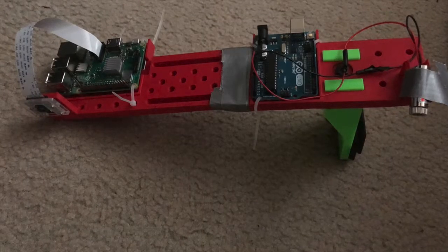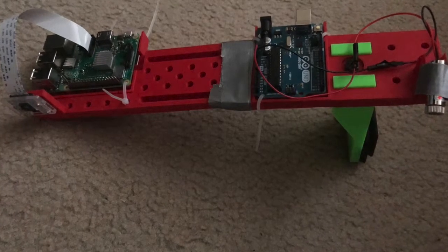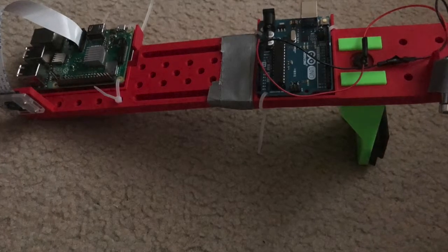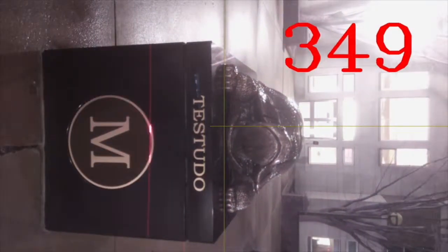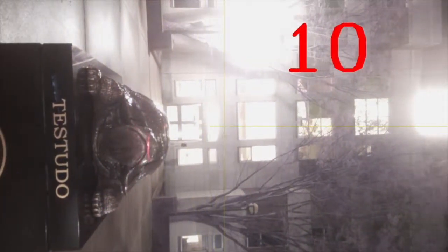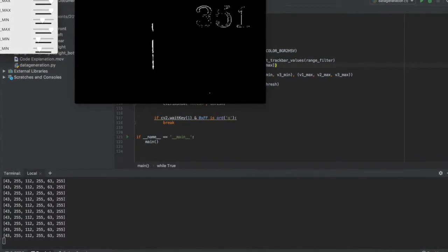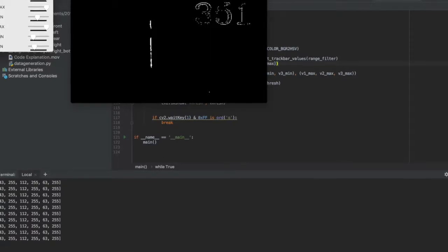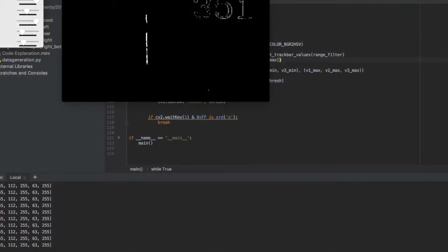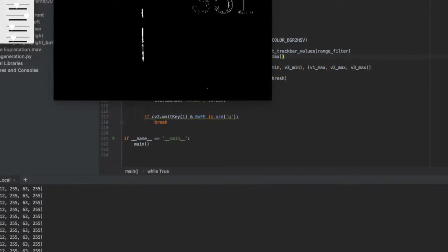In the context of this project, I built a simple LiDAR system that takes 3D measurements of the Testudo statue in front of Van Munching Hall, using a line laser and a Raspberry Pi. I took measurements at integer degrees on all four sides, resulting in about 30 measurements per side. By applying a color mask on the images, I was able to use computer vision techniques to find the number of pixels between the identified laser line and a datum axis on the screen. With simple geometry, the Python script can calculate the distance from the source to the statue.